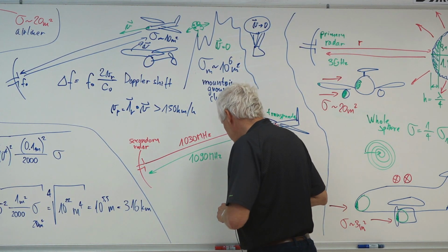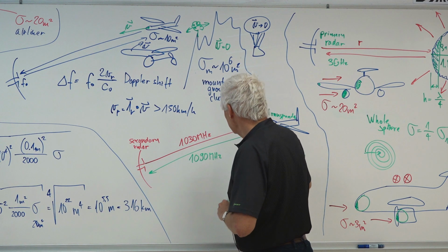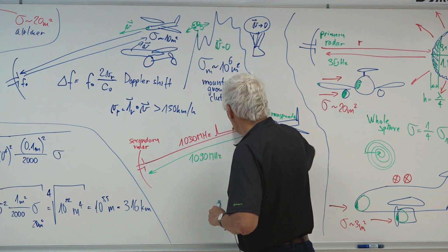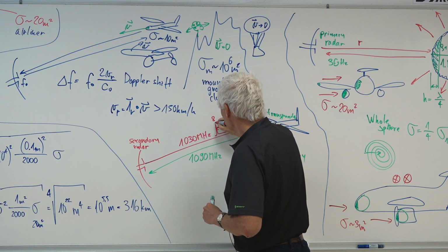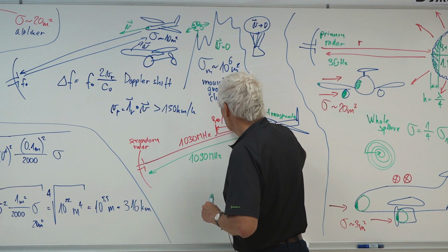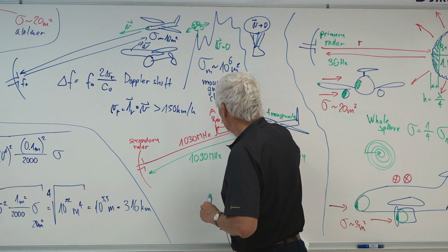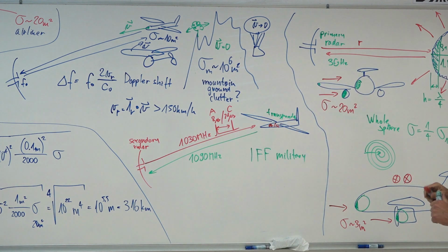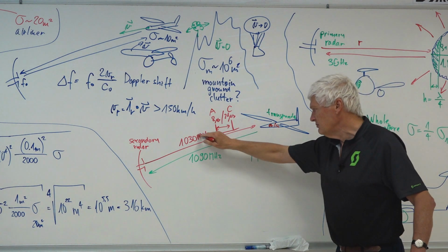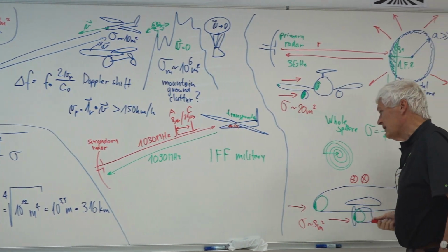And actually the question here is just 2 pulses at a known separation. The separation is 8 microseconds or 21 microseconds. This is mode A, mode C. Mode A was actually also used for IFF in the Second World War. All these things date back to the Second World War, so that's the reason why these frequencies are low by today's standards.